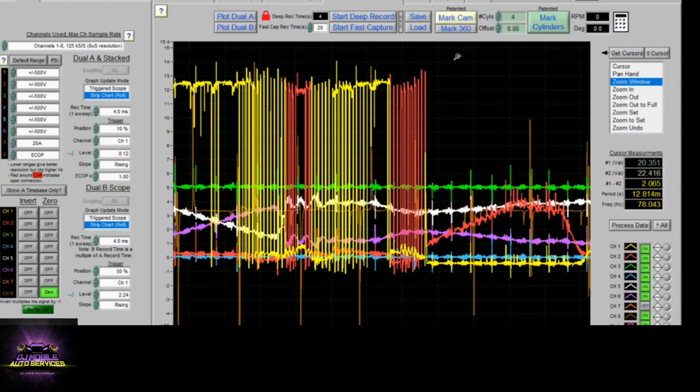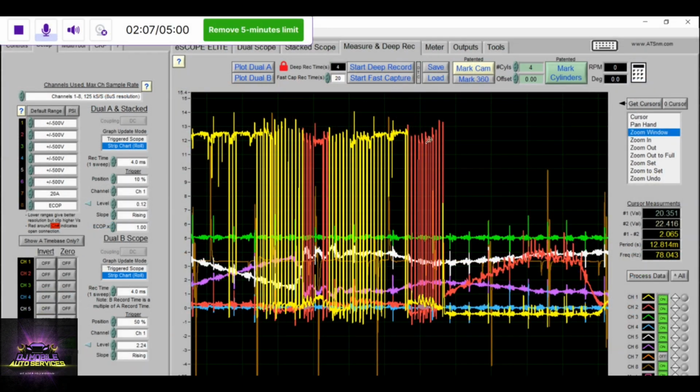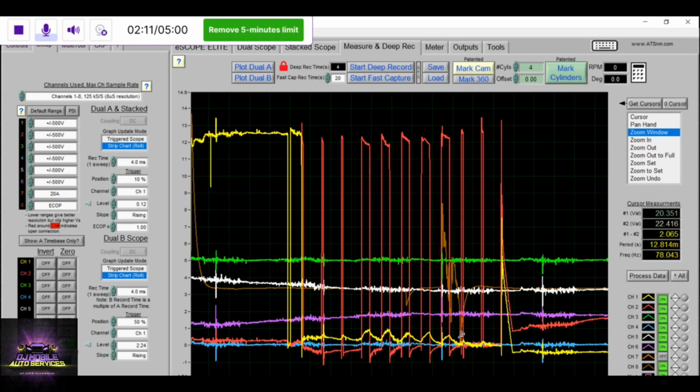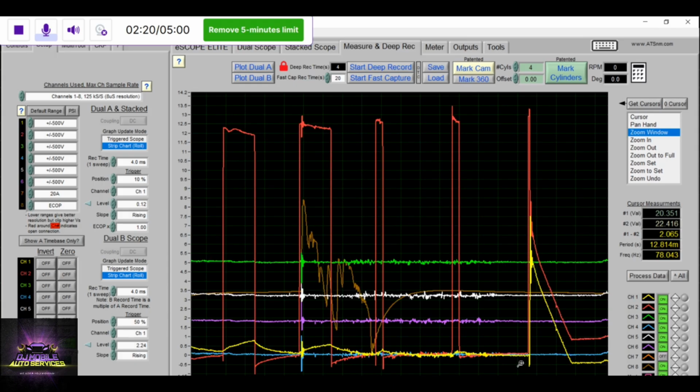The ECU is sending voltage to the motor to open and close the plate, but for some reason it's seeing high resistance, so it's shutting down. And if you get high resistance, you're going to have low current. I believe we may have to replace the throttle.